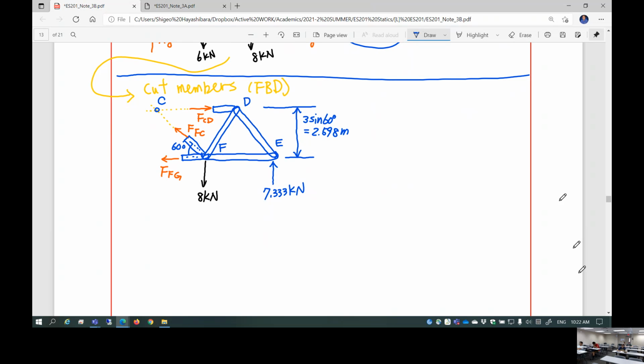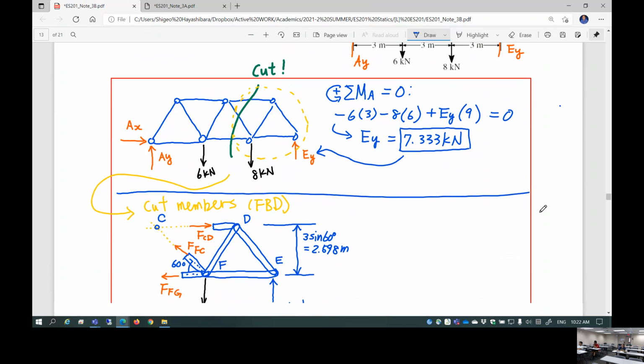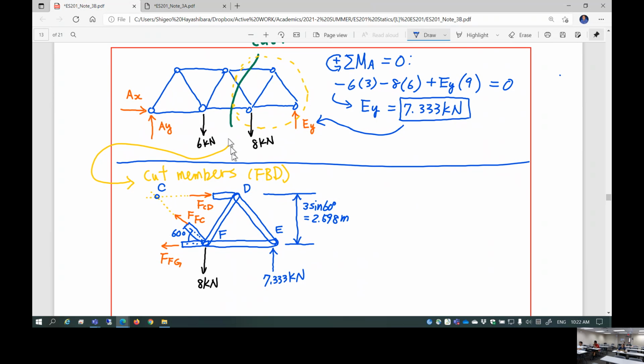In other words, if you assemble this structure, connect it up with that, those 3 forces all disappear because it's all internal force, right? Okay. So now what you're trying to do is virtually introduce the cut, exposing those internal forces so that you can apply summation of force and moment to find those unknown internal loadings. That's what you're doing. This is called method of sections.